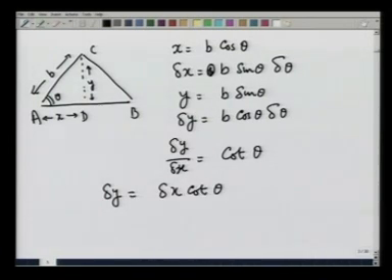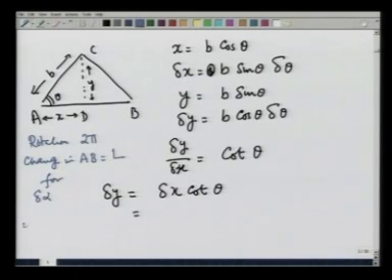How much is delta x? That is equal to nothing but the change in the length AB for rotation. Let me just write on the side, for a rotation of 2 pi the change in AB is equal to L. So, for delta alpha it is going to be L over 2 pi times delta alpha.